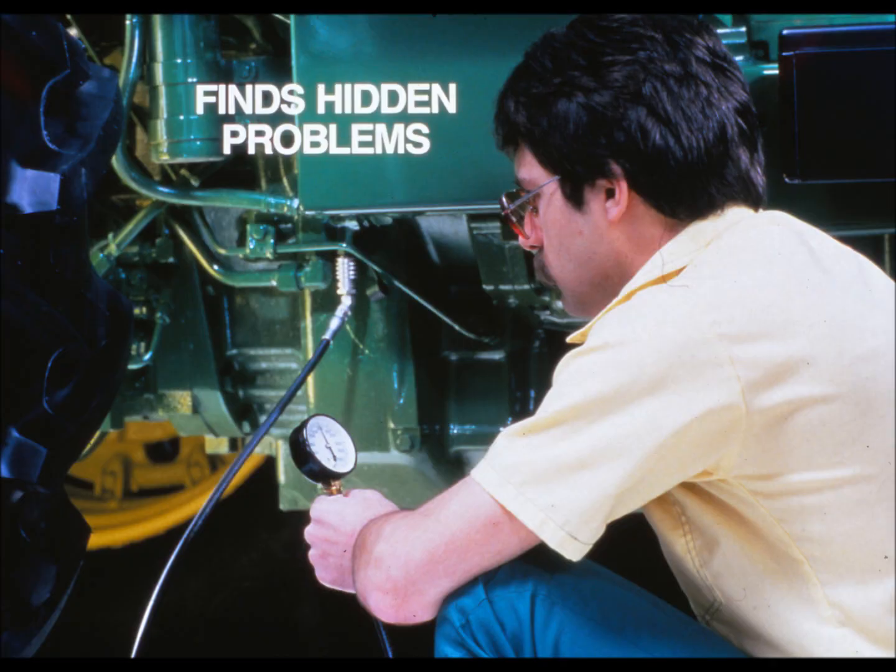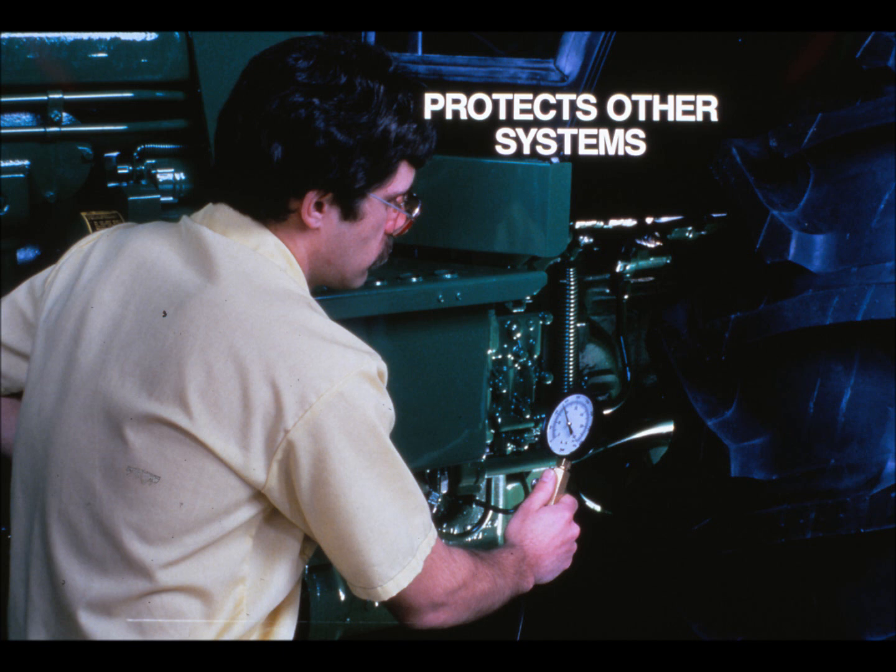The hydraulic diagnostic procedure has several advantages over other methods. One is that larger John Deere tractors have large capacity pumps in their hydraulic systems. A substantial leak may not cause noticeable symptoms because pump capacity will make up for it. The hydraulic diagnostic procedure will identify minor malfunctions before they become major problems. Problems in other tractor systems may be related to the hydraulic system. For example, low lube pressure could cause a failure in mechanical components of the transmission. The hydraulic diagnostic procedure can identify those kinds of problems and prevent repeated failures in a mechanical system.